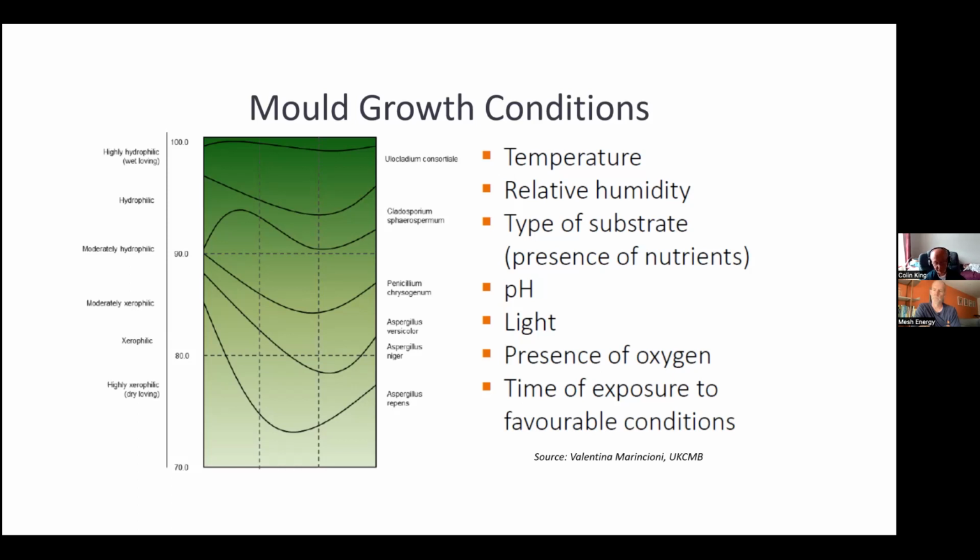And what you also find when you do internal wall insulation is it's very difficult to deal with the thermal bridging. Whether you're looking at intermediate floor level or the connection of the wall to the roof or the wall to the floor, you've then got to reach this internal critical temperature factor of 0.75. Otherwise, you run the risk of getting condensation and mold on adjacent surfaces.